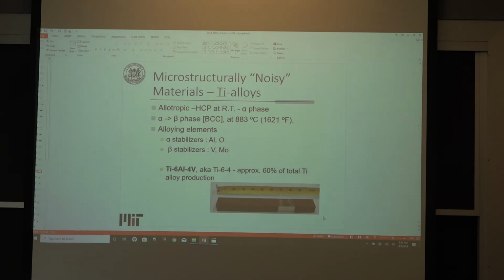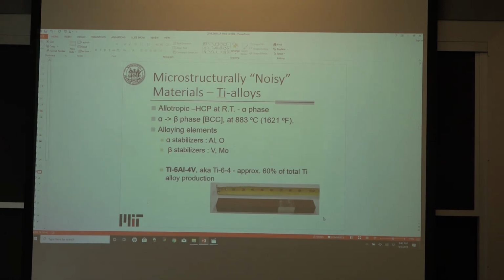All right, this is your phase diagrams. This is your basic material science, intro to material science. What happens is, though, it leads to issues with the inspection techniques. And what you're seeing in this image here, this is what's called the alpha case. So it's the alpha phase, but it's basically a protective layer that builds up over the titanium to keep it from corroding. Then when you look at it when it's milled, it looks shiny and it looks like what people generally consider when they think of titanium.